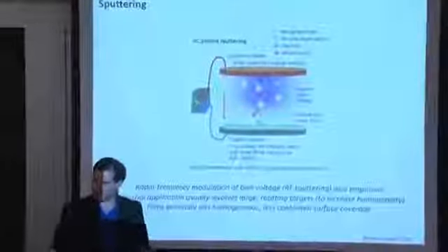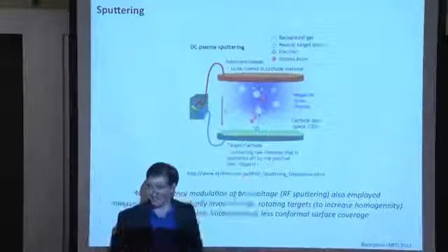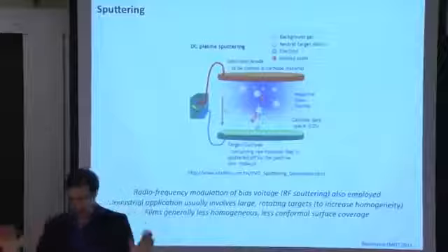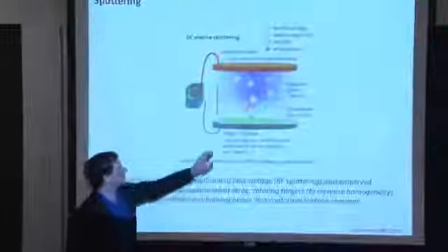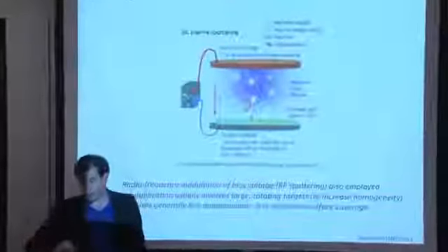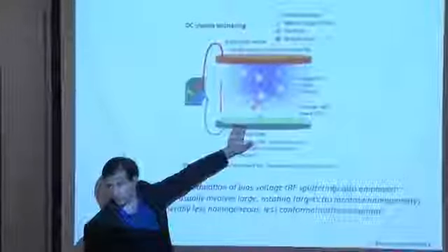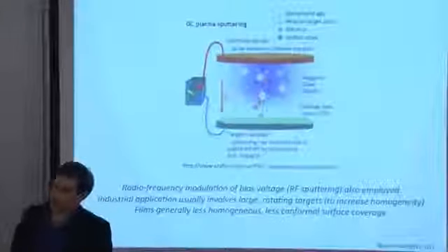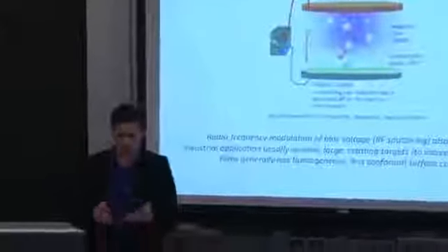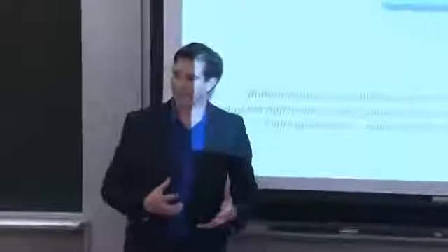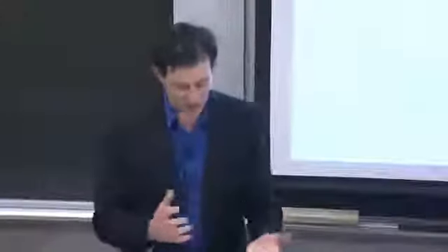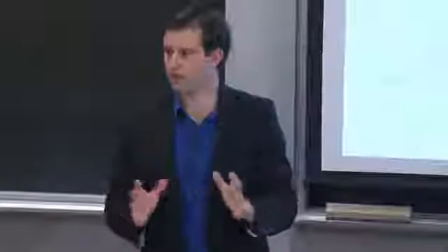There are things you can do to minimize cross-contamination. You can have a chimney around your target to prevent flakes from coming down. You could sandblast the sidewall coating and so forth to prevent gunk from building up around the side. But you're still going to get a lot of cross-contamination here. And furthermore, the purity of your film is dictated by the purity of your target. And if you go online and look at Alfa Aesar or Cerac or some of the big metal selling firms, which are essentially from where the target manufacturers are purchasing their precursors, and then they can pack them and make their targets, the target purity, or the metal purity, is only on the order of maybe 2 nines to 6 nines pure, typically within that range.